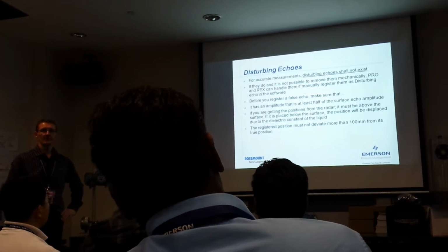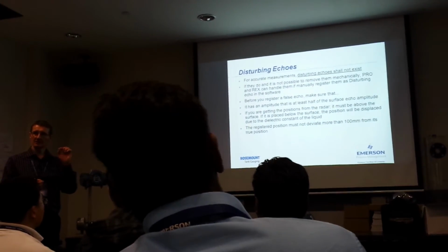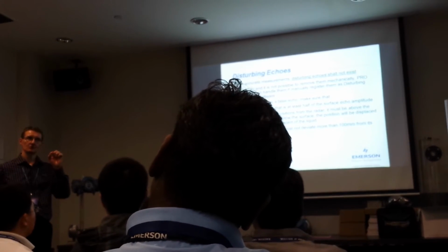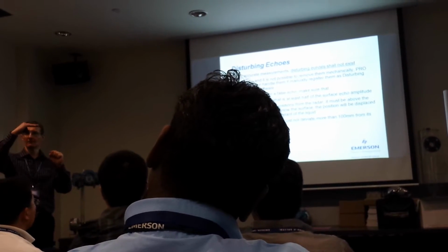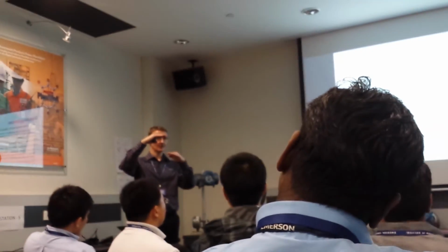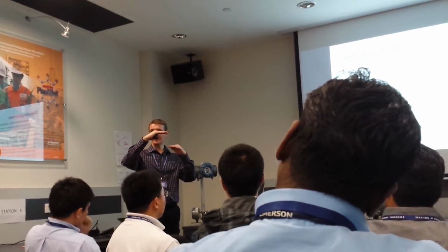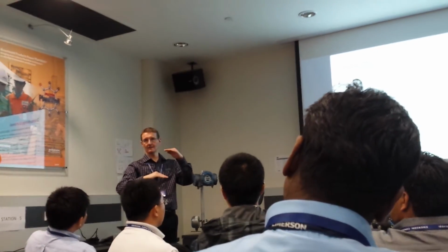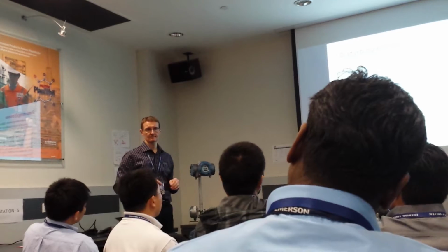The important thing is that when you tell the radar where this disturbing object is, you should not have any liquid above where you have the disturbance, because then the radar cannot see exactly where it is. The liquid must be under the point. Very important.